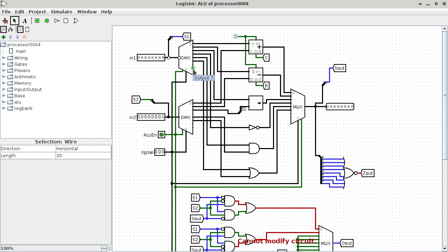So how many bits do I need to specify 1 out of 8 possible outputs? Or I can also ask, if the range of values I need to represent is 0 to 7 in decimal, how many bits do I need to specify that range of unsigned values? 3 bits. That is correct. Because 111 is 7, and 7 is the largest value that I need to specify here.